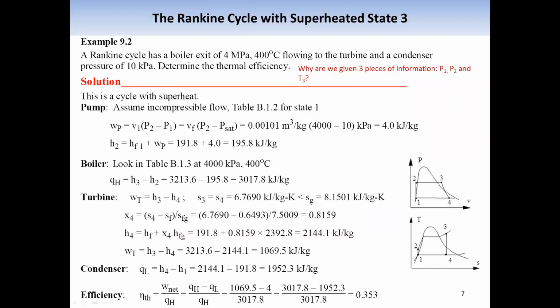Then the efficiency can be estimated based on the definition, that is the net work done divided by the energy absorbed at a high temperature. Based on the first law, the numerator can be replaced by the difference of QH minus QL, so we can calculate the thermal efficiency.